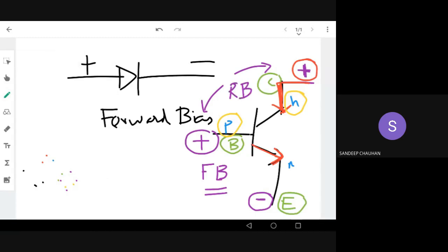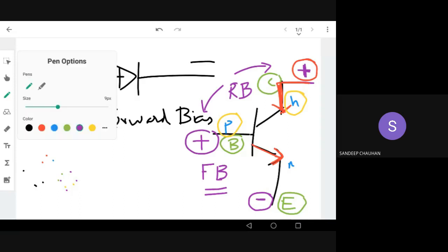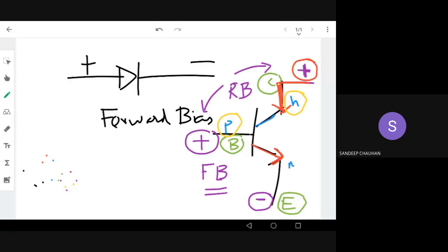Why have I said this? Because the collector region has to push some charge. So the N region of this PN diode on the left, which you are seeing, has to be reverse biased. That means the base has to be given a lower voltage and the collector has to be given a higher voltage, right? Because there's a diode here. You can see the diode here. I'm drawing it here. So P and N. This is the P and N. This is the diode actually, P and N. So this has to be reverse biased, right?